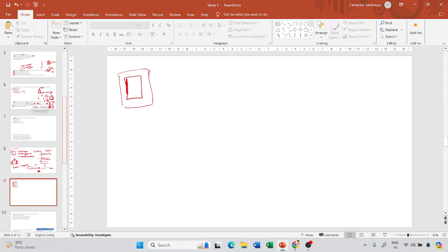Now you have to hold the sample at that temperature, and then apply Haversine loads at different frequencies. And how will you apply these different frequencies? You should always start from the highest frequency and then go to the lowest frequency, which could be 0.1 hertz or 0.01 hertz.